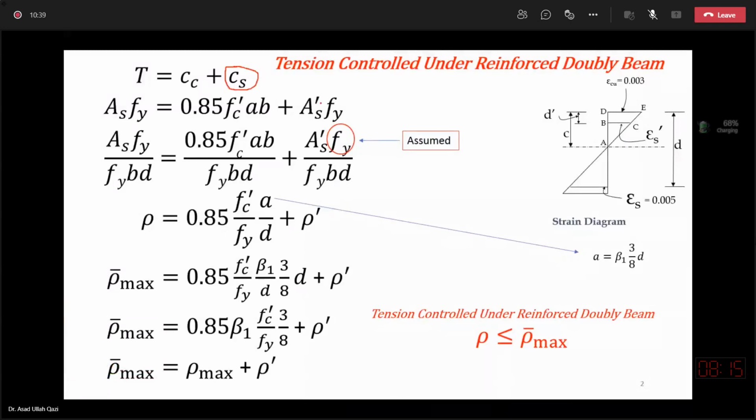I substitute for T as AS Fy, working on a condition that my tension steel is at yield or above yield. In calculating CS, I'm using AS prime for the compression bars area, and I'm assuming that compression steel is also at yield when writing this equilibrium equation.